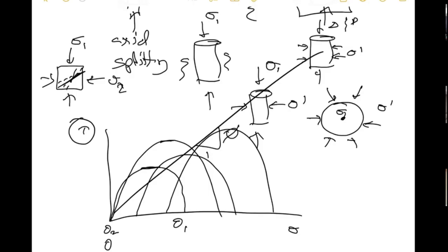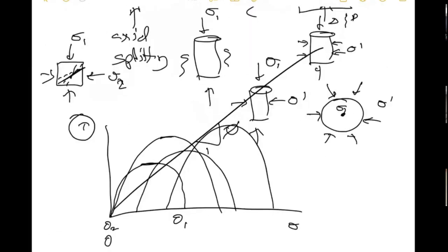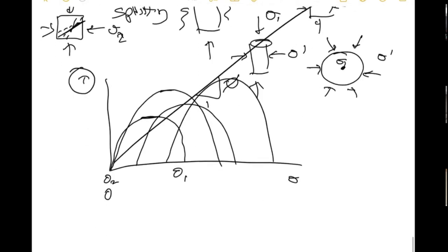So that's also a typical thing. It's called a friction angle. This is called a Mohr-Coulomb idealization of the rock strength. Because remember, the rock strength, the UCS, is not enough. You also need to know how much stronger it gets as you confine it. And that's measured by doing these tests, triaxial tests at different confinements, and then interpreting these values in terms of these Mohr circle failure envelopes, and you get something like this.